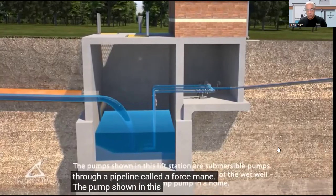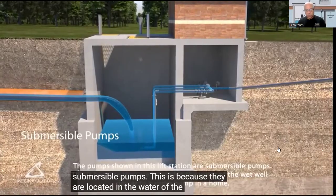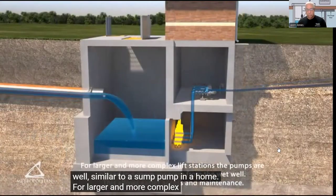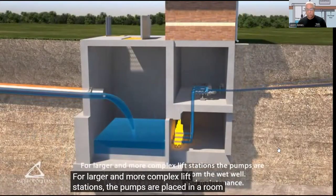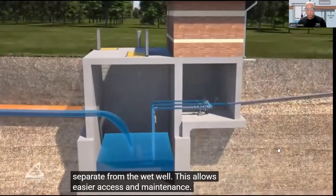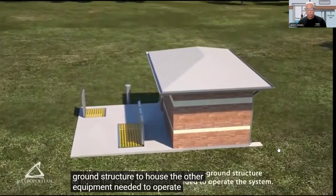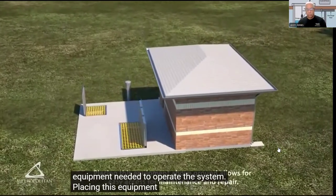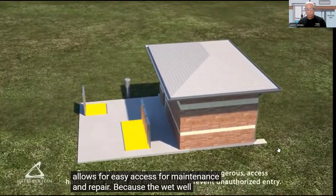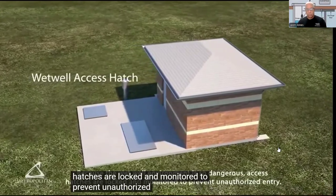The pumps shown in this lift station are submersible pumps. This is because they are located in the water of the wet well, similar to a sump pump in a home. For larger and more complex lift stations, the pumps are placed in a room separate from the wet well. This allows easier access and maintenance. Lift stations will often have an above-ground structure to house the other equipment needed to operate the system. Placing this equipment above ground allows for easy access for maintenance and repair. Because the wet well environment is so dangerous, access hatches are locked and monitored to prevent unauthorized entry.